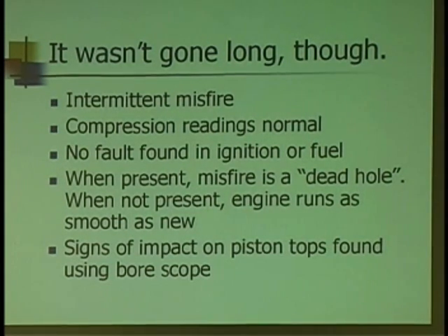Complaining of an intermittent misfire. Check engine light was on for a P0304. When he got it back in, though, the car was running beautifully. Compression readings were normal. He couldn't find any problems in ignition or fuel. They did get it to fail once. And when it failed, it was like a dead hole, no question.